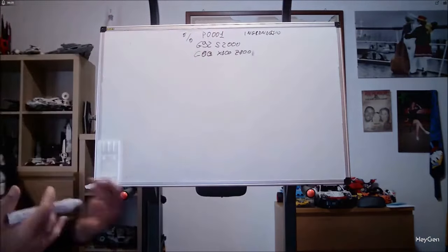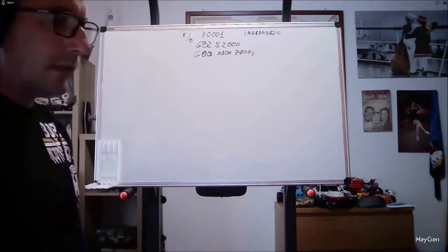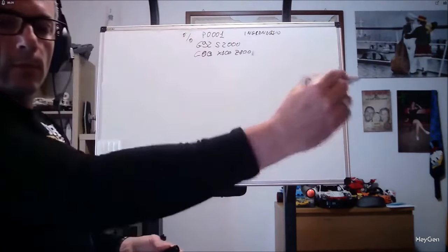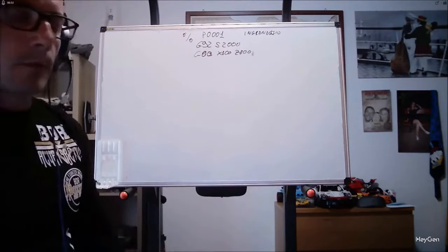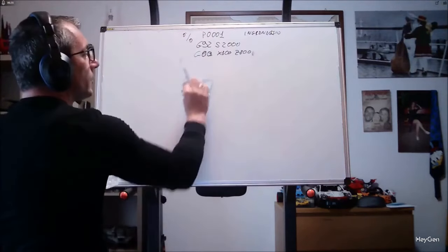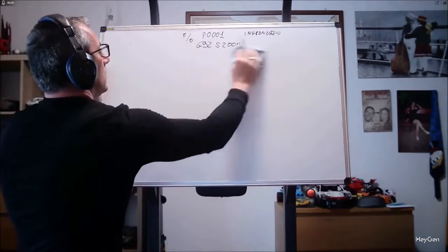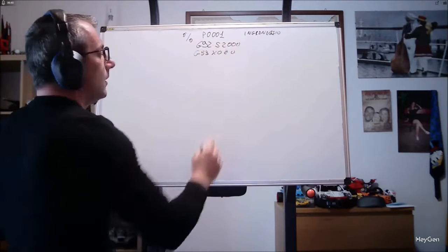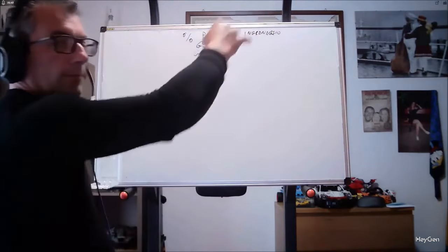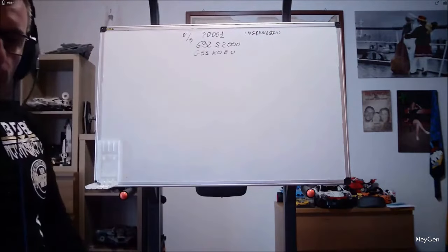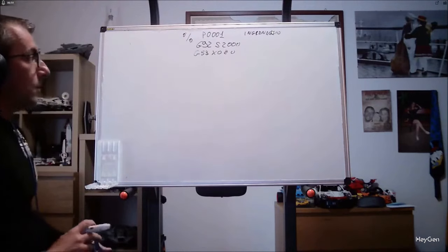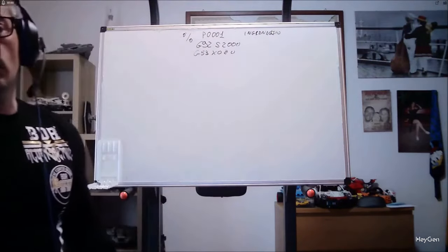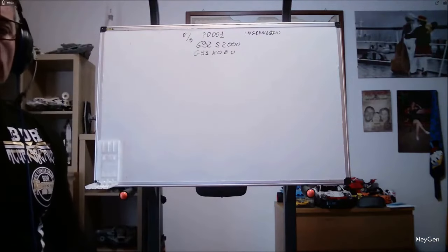I foresee an approach to the first movement block, first in Z and then in X. I will explain this too. I don't define this as important, but know that if you find it, especially on Fanuc, I remember this well. G53, X0, Z0 tells the machine to go to its origin point, which is usually high and far from the spindle. After that, we need to start thinking about calling the tool we will work with at the beginning of our piece.